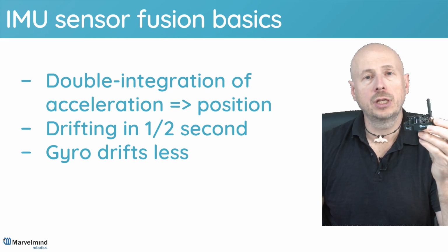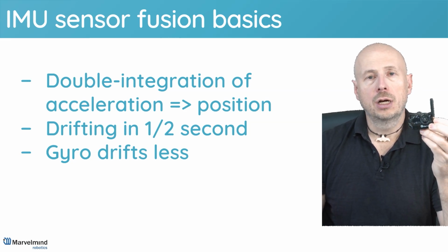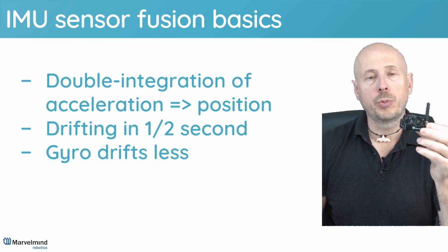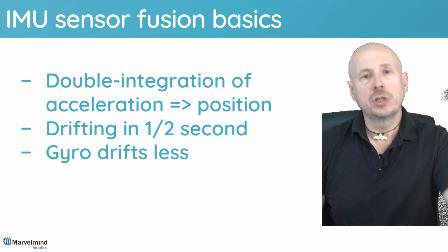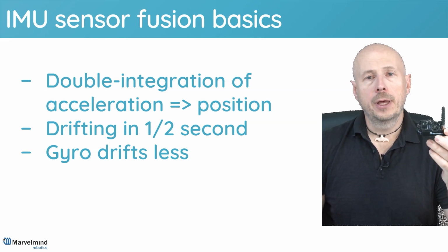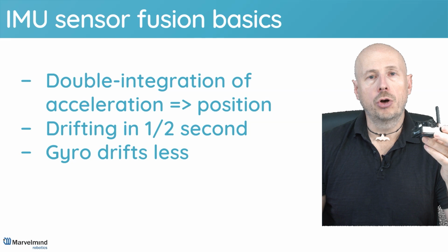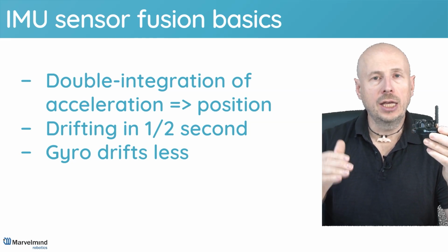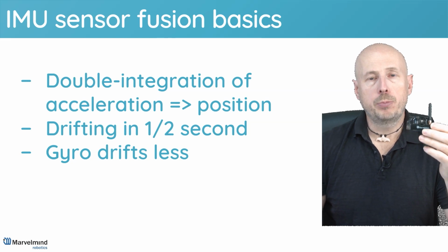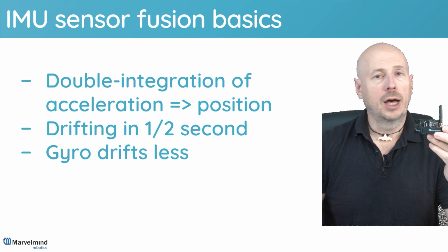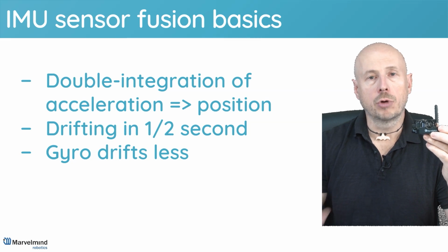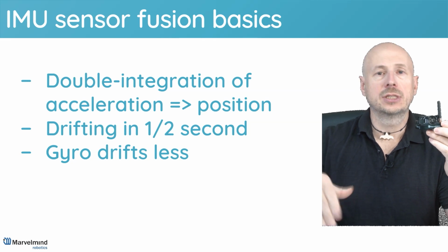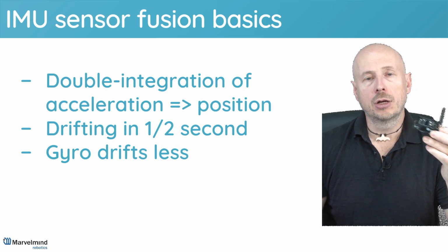Okay, if you calibrate it well enough, it's around half of the second, sometimes 1 second. So within 1 second, calibrated beacon will drift away. So this is why, purely based on inertial measurement unit, without any sensor fusion, without any cancellation of the drift, purely IMU-based systems, I don't know any of them really working. They are all using some sort of calibration. No, not calibration, some sort of cancellation of the accumulated drift.